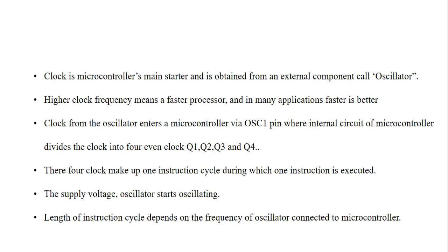The microcontroller will react faster, but it also requires more power consumption. So the clock from the oscillator enters the microcontroller via the OSC1 pin, where the internal circuit of the microcontroller divides the clock into four even clocks Q1, Q2, Q3 and Q4.